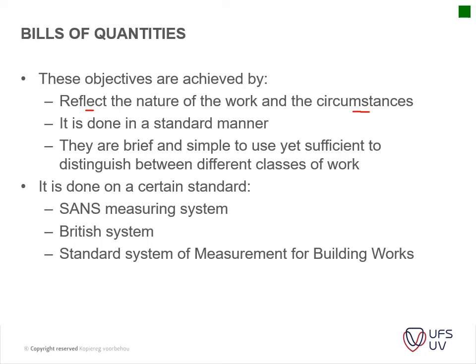It's very important, if you think about it, because if you leave that for assumption and you have 6 different contractors tendering on a project, for instance, and you assume that there's no hard rock and another contractor comes in and allows a certain percentage for hard rock, then it will be difficult to evaluate the tenders and get the right comparison, because one included this and one excluded this, so it becomes difficult to evaluate the tenders.